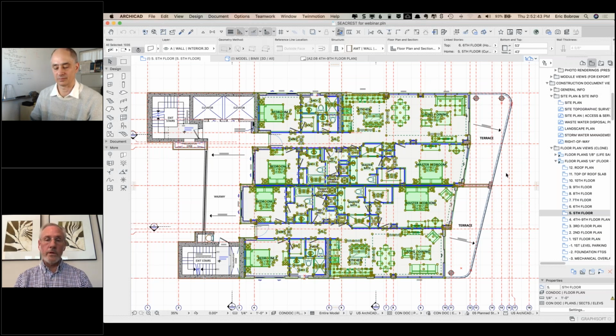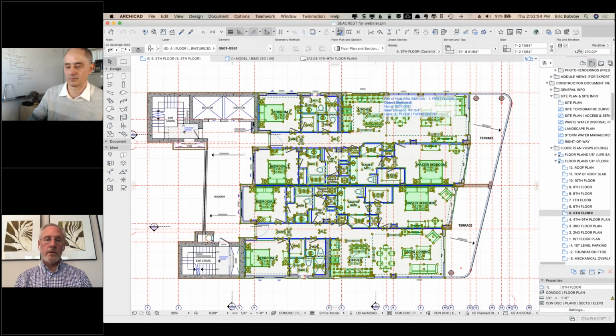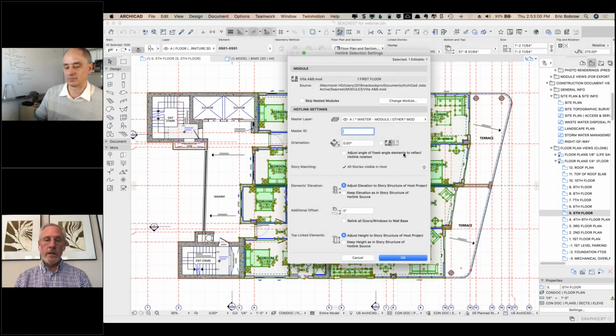They do have to handle some wind loading, of course, because you can get hurricanes there, but they couldn't be connected with a solid structural connection to the slabs above. So basically the structure itself would stand without those sidewalls, just on the columns and the slabs. So we had to provide a disconnect there. And even the rebar is in sleeves that can actually move if the building starts to move a bit with an earthquake or wind loading.